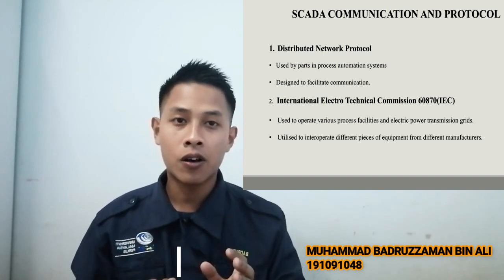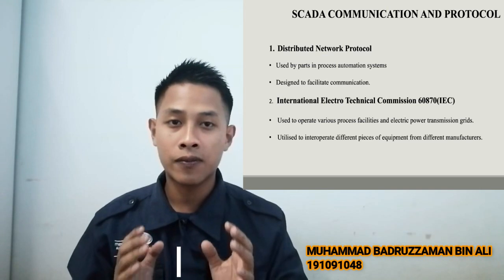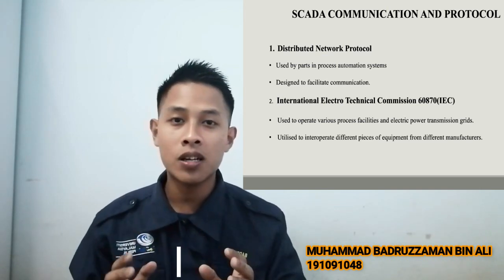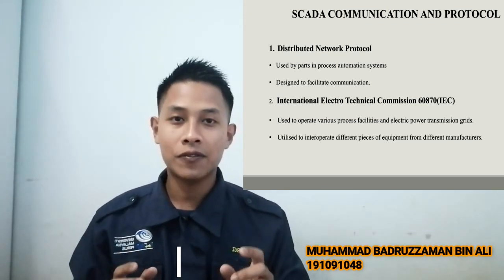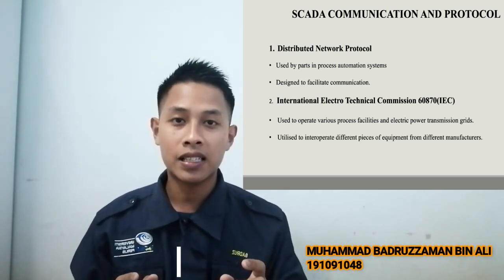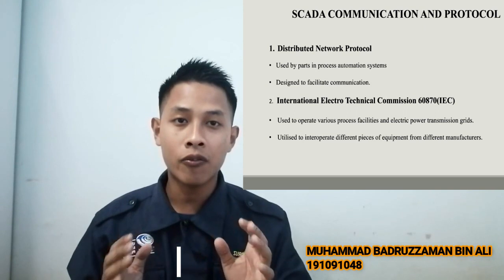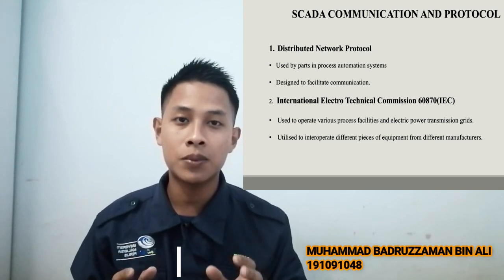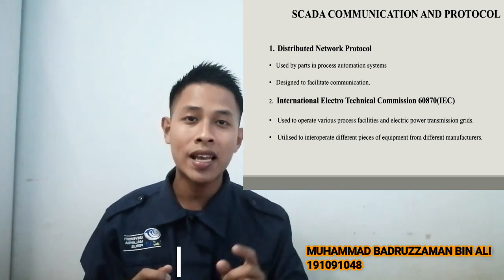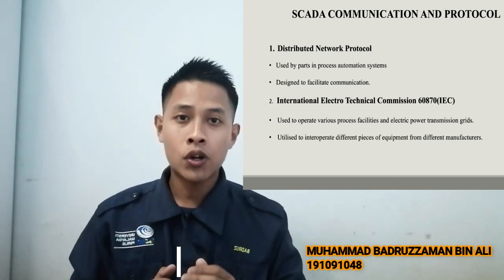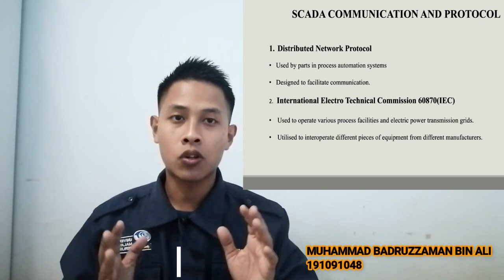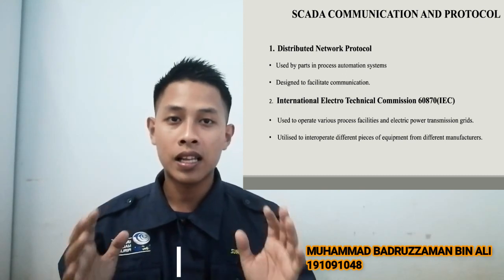The six components of IEC Standard 60870 define general information about the standard, operating circumstances, electrical interface, performance standards, and data transfer. A communication profile for telecontrol messages between two systems, directly coupled, is provided by IEC 60870. Through connected telecommunication, this protocol offers telecontrol and teleprotection of electric power networks.